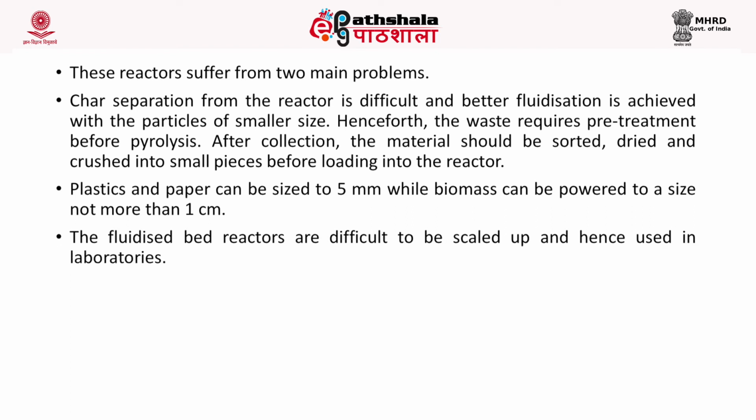The waste requires pre-treatment before pyrolysis, and after collection the material has to be sorted, dried and crushed into small pieces before loading into the reactor. Plastics and paper can be sized up to 5 mm, while the biomass should not be more than 1 centimeter before adding into the pyrolysis unit. The fluidized bed reactors are very difficult to be scaled up and hence normally used in laboratories.